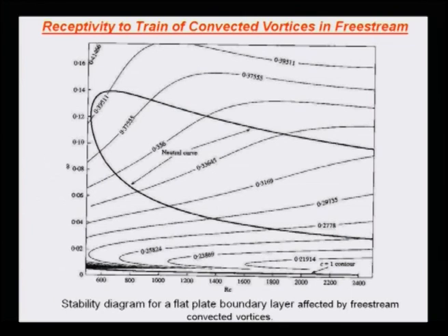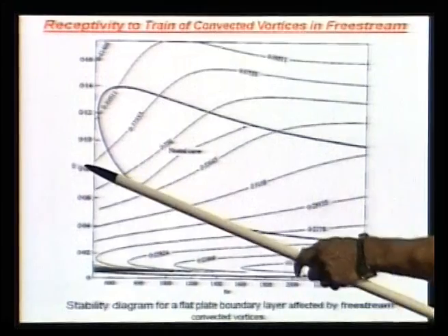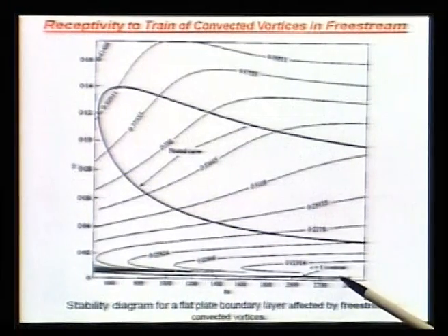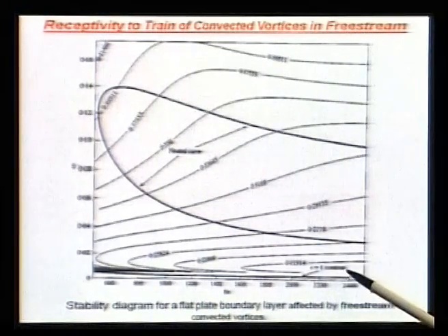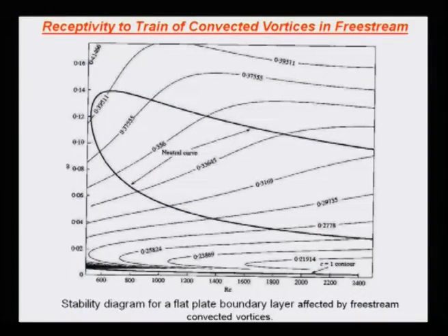That means the vortex is moving at a speed of u infinity, and that line corresponds to here in the Re-omega naught plane, which is so far out of the neutral loop. So you would know it's very stable. So it plays little or no role at all in exciting a response field.